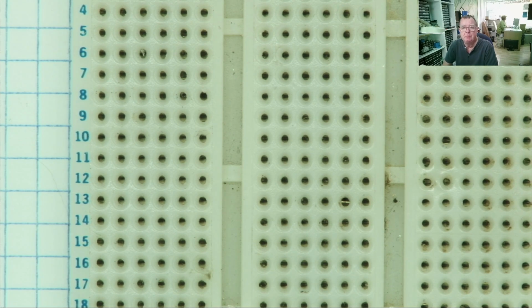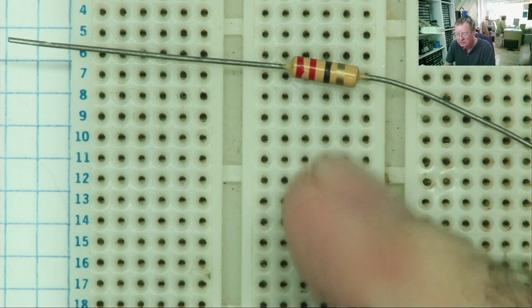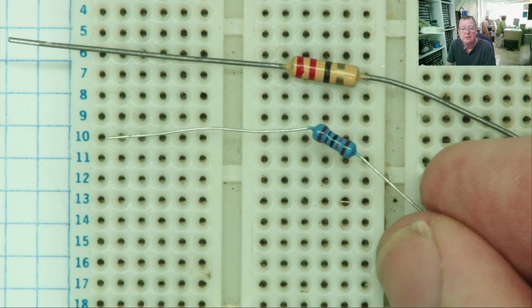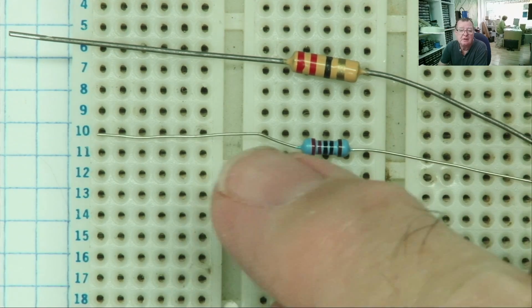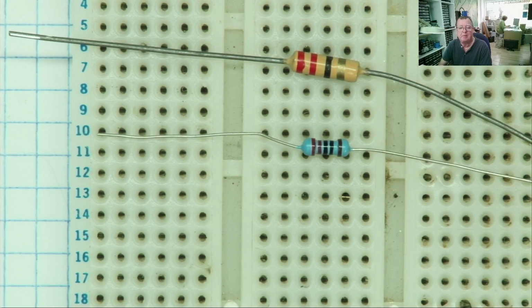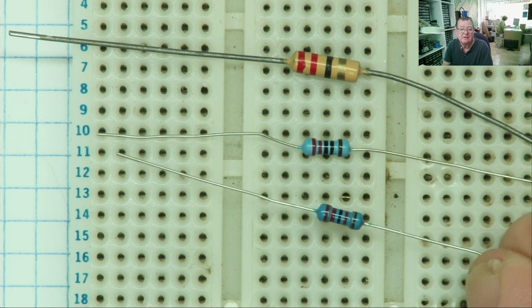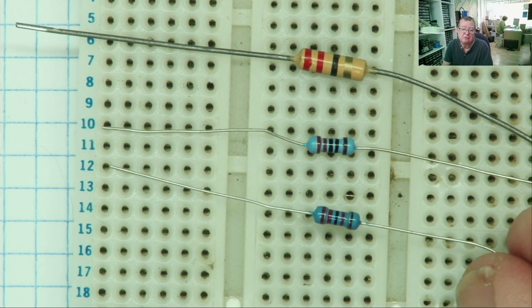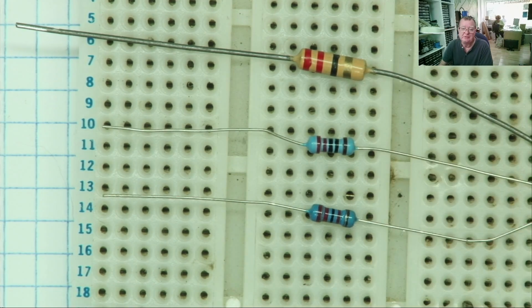Of course, we need a few components as well to conduct these experiments. So we're going to have some resistors. We talked about resistors earlier, so you'll know about these. This is a 22 ohm resistor. This is a 220 ohm resistor. These are not brown, they're red. My camera picks the colour up wrong. This one is a 22 kilo ohm resistor, or 22,000 ohms. So we have an increasing value, a few resistors there we can play with.